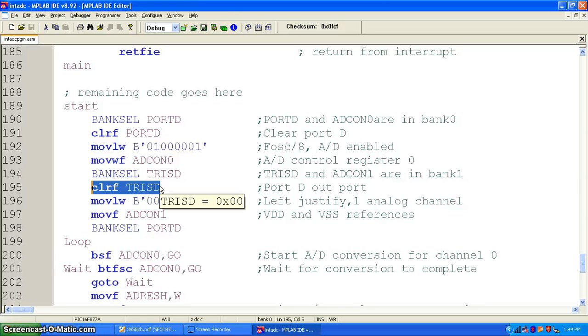So what I do is, ADC output I output onto port D. So according to the ADC output, the port D contents will vary. Now next is this format I load in ADCON 1. So again, if you check the ADCON 1 format, if I make it 1110, so what I am trying to do is